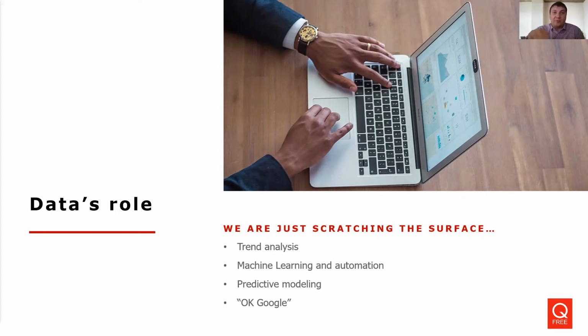Also, trends can help track problems. So if you see in the trend, or the system's analyzing in a trend analysis, that the traffic congestion is slowly getting worse, then slowly gets better, it's probably just a peak hour issue. But if it finds during that trend that traffic just jumps up and is extremely congested all of a sudden, then you might have a form of automated incident detection to tell you something's wrong.